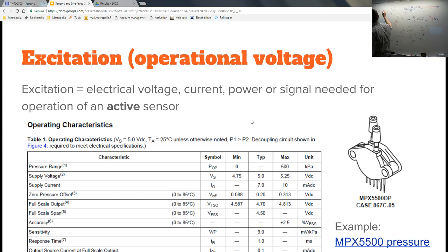That's the microphone. Those are big membranes. One is solid, one has holes so that the air can go through. But anyway, you usually have an excitation voltage here, and there is some way to measure the current, and the distance changes, meaning that it changes the capacitance.